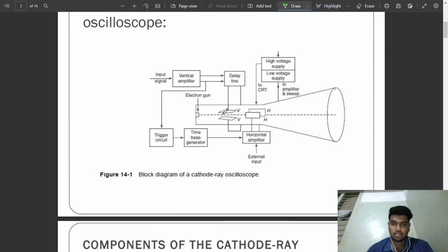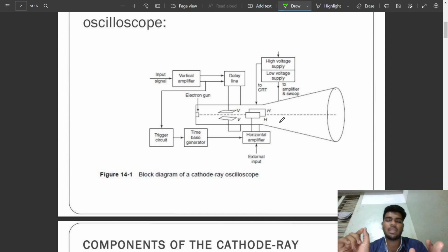We know that the electron beam passes so fast, like fractions of seconds. As soon as the coil gets heated, the cathode rays are given out. As the input is already given, the focus electrons get the voltage, and then it is focused in a single stream of beam after passing through the vertical and horizontal amplifier, and output is given on the fluorescent screen. Now, how should be the voltages of vertical and horizontal amplifier?